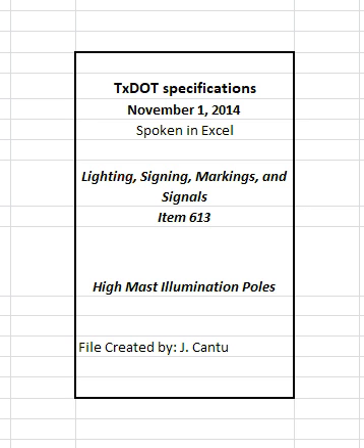Provide 85% minimum penetration in longitudinal seam welds at other pole sections. Provide longitudinal seam weld and fit up that will minimize acid entrapment during later galvanizing. Use at most 2 longitudinal seam welds in each section. Permanently mark each pole base plate with the insignia or trademark of the fabrication plant. Place the mark on the pole base plate adjacent to the handhole access compartment.